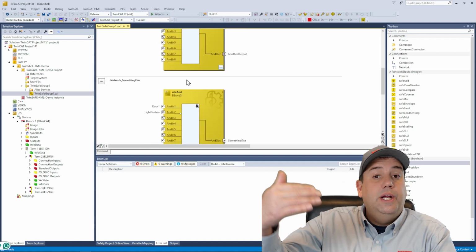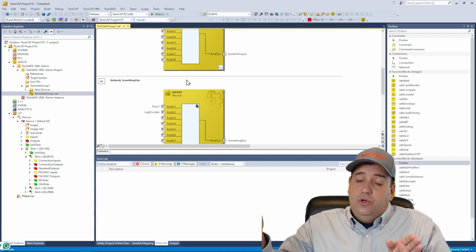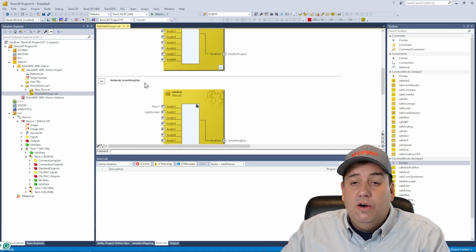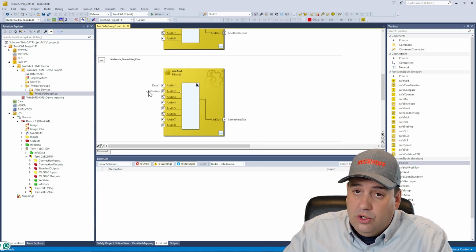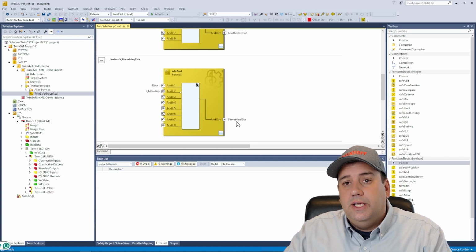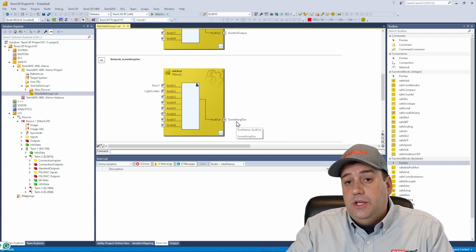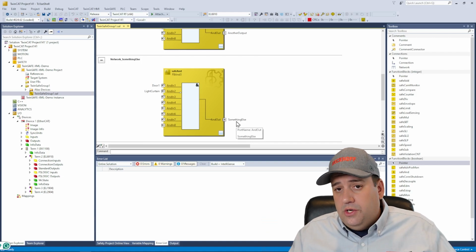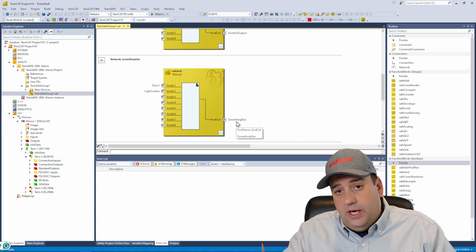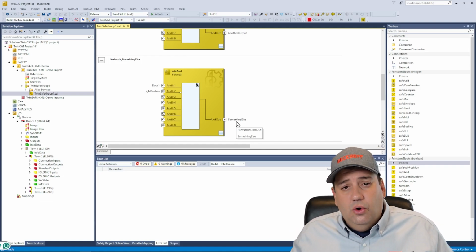And we now have 3 networks because all 3 actors had a way to trigger them. So in our final network, we see something else where door 1 must be true, light curtain must not be true, and something else. So this is one way that you could use a VBA script either within a Microsoft application or creating your own application in order to auto-generate XML files that can be used within TwinSAFE. Hopefully you found this helpful and can use this in your applications.